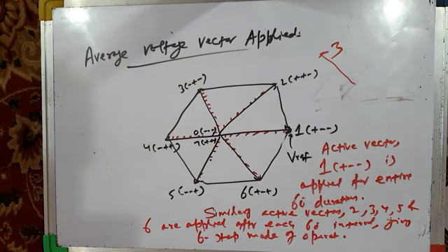And we have seen the variation of the angle of the rotating reference vector. We have seen the variation of the magnitude of the rotating reference vector, how it varies. And we have also seen that as we increase the modulation index with over-modulation, the inverter output voltage no doubt increases. The depth of over-modulation increases, but at the cost of more and more distortion.